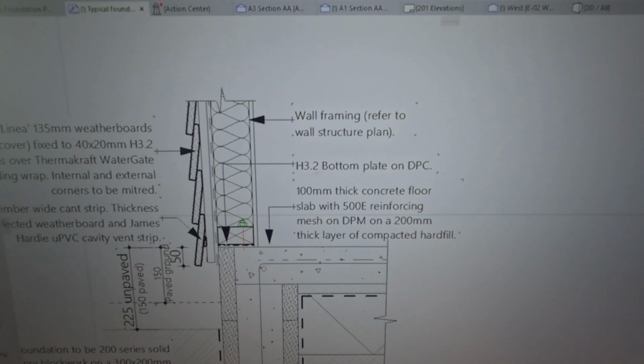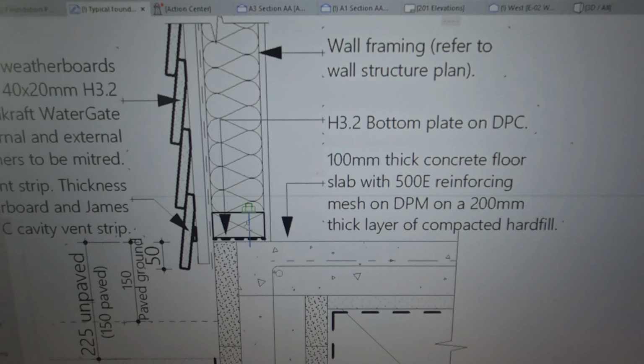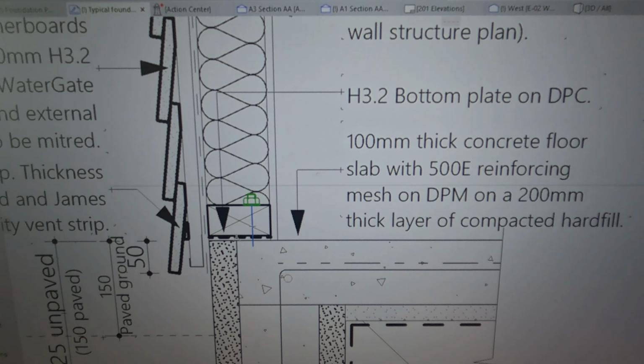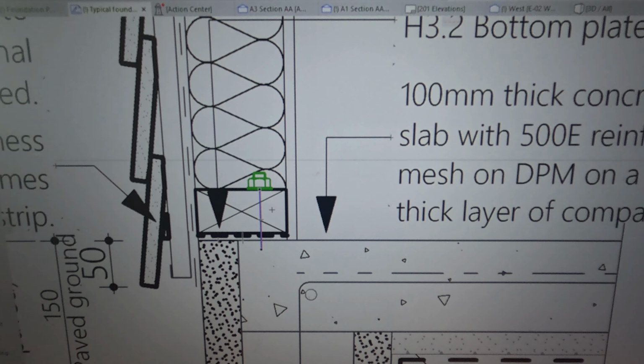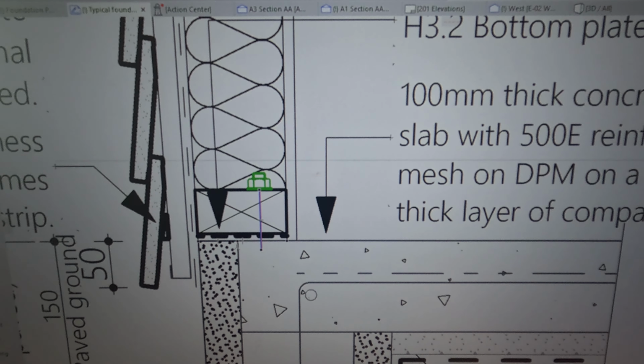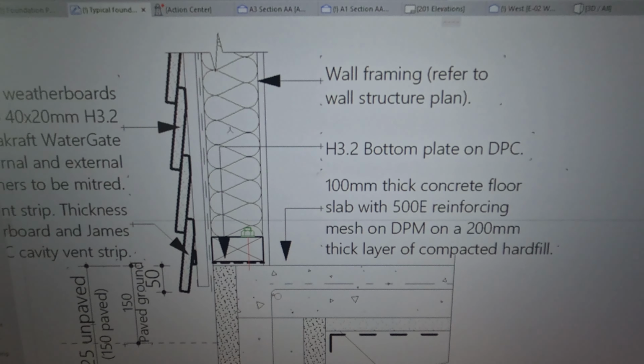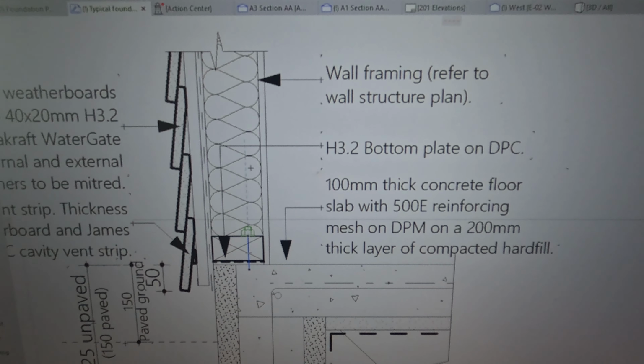And of course, your walling, I'll talk briefly about the wall. So anytime you have timber connecting to concrete, you must have DPM. We normally put DPM between the bottom plate and the timber. This is to prevent moisture from egressing into the timber. Then you have your timber framing, which is 90 by 45, but nowadays sometimes it's actually advisable to do 145 by 45 timber studs. They basically increase your thermal capacity, energy efficiency, because then you can use larger insulation.